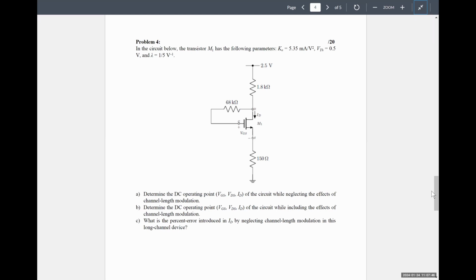That is my expectation for you for the exam, to literally just be able to analyze the bias circuits that I've given you. You'll be provided an equation sheet that should have all of the equations for the bias circuits and all of that kind of jazz. But even if I didn't give you an equation sheet, it's always going to be KVL along the left-hand side of the circuit, KVL down the right-hand side of the circuit, set up a system and solve.